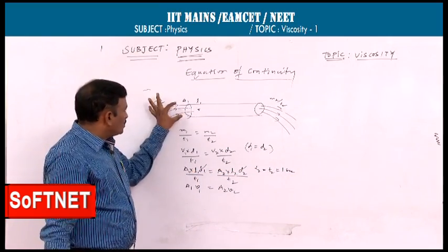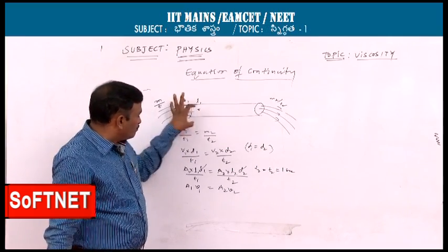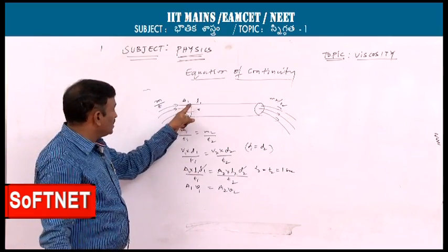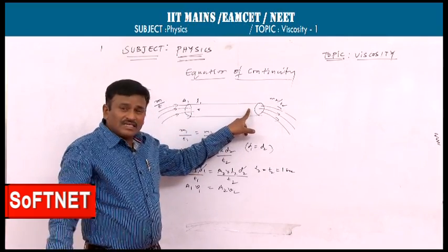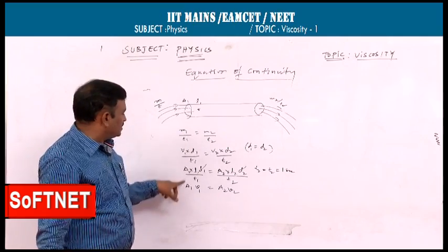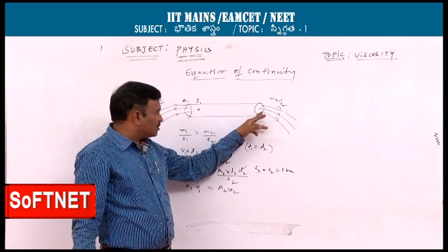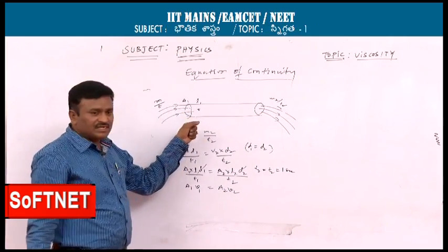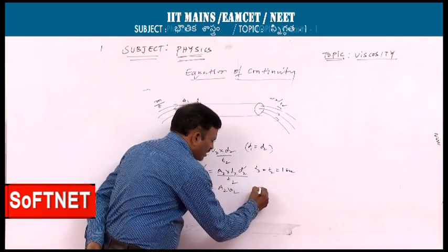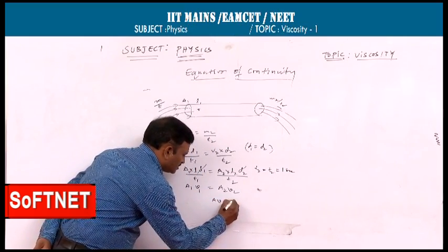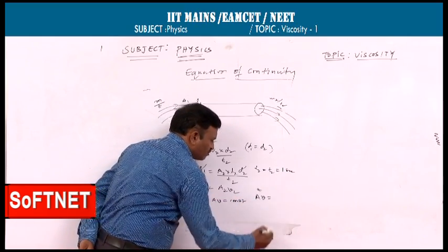Within 1 second, how much flows at each place is not the same, so the velocity will differ, but the volume rate is constant. The displacement covered in unit time is different, but together the volume rate A1 V1 is a constant. At another place the area may be less and the velocity more, or the area more and the velocity less. They are inversely proportional, so finally AV is constant. We have to remember that AV is equal to the volume rate.